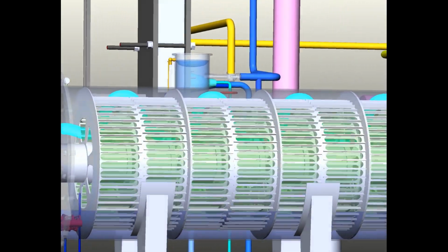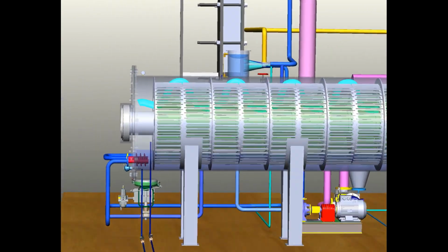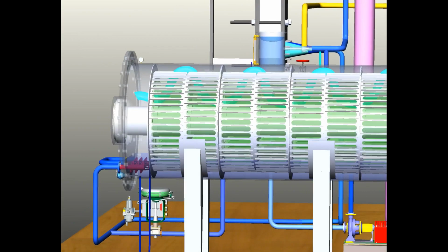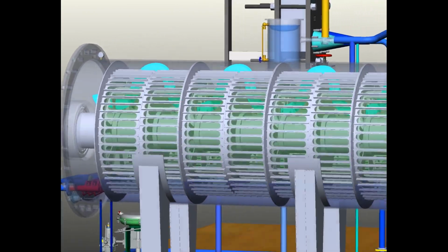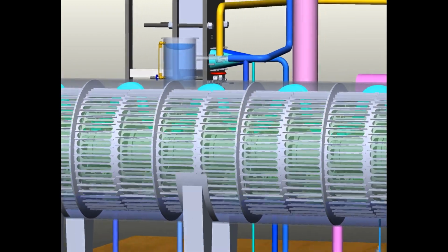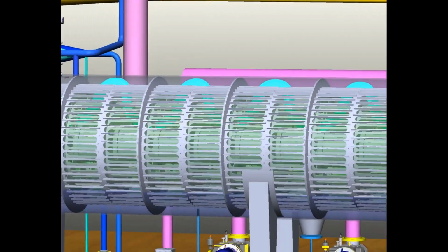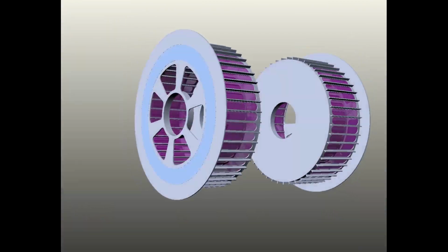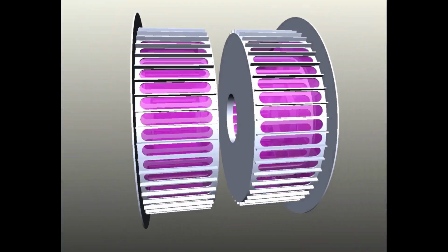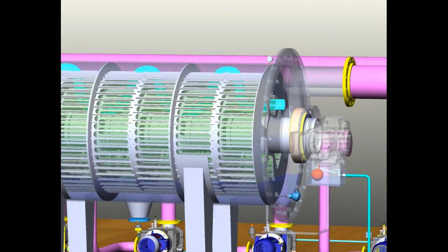Unlike distillation columns, this apparatus is located horizontally, and the nozzles are located in the annular layer, which rotates, periodically dipping into the liquid in the lower part of the body. Near the end of the apparatus, heat exchange tubes through which a room temperature coolant flows, steam is generated, which then passes through the nozzles. The partitions between the mating sections of the nozzles are designed so that the steam path has a zigzag shape.